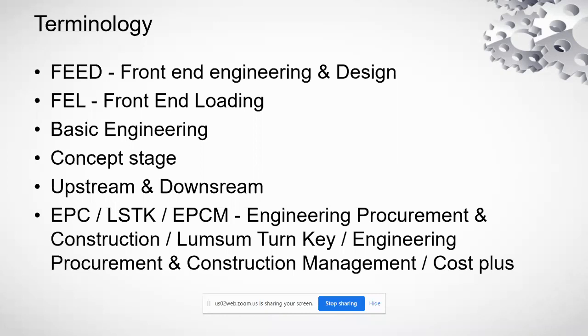It's just called front-end loading. Then basic engineering, concept stage. Concept stage is another name for FEED stage or FEL stage or pre-FEED stage. Concept stage is a typical word used by the national oil company of Oman, Petroleum Development of Oman. FEL is a typical terminology used by Aramco in Saudi Arabia and other companies there.